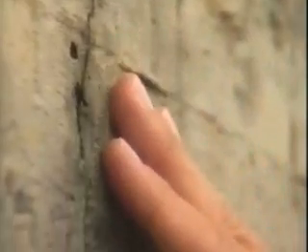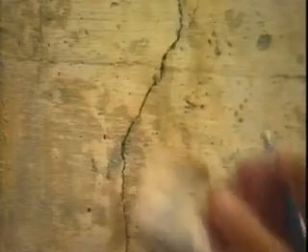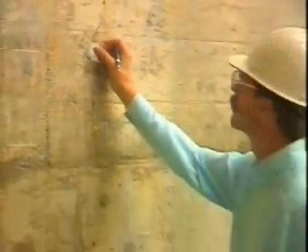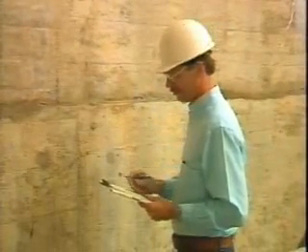Structural cracks are the most serious, since they indicate overstressing and could affect the structural integrity of the dam. These cracks are often wide, run at an angle to the major axis of the dam, change direction abruptly, and are associated with noticeable displacement. Be especially concerned if the structural crack is new, or if it has increased in size. Whatever the type of crack, if it could be significant, measure its length, width, and any displacement, and describe it fully in your report.